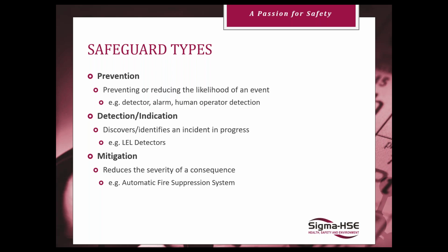You've got gas detection in the area at 25% LEL. It alarms and alerts operators to know, there's an issue here, there's a leak, something needs to be done to address this. Detection, indication, something's already in progress, but you can detect and respond that way. Fire detection, if you've got pressure indication in a vessel that's not supposed to see pressure, maybe a vent stack,